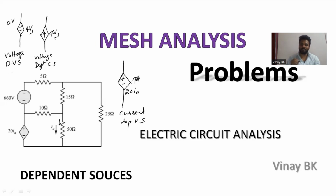One thing you should remember: if there is a dependent source problem, you should search where it has that parameter. For example, 20 IA. Somewhere in this circuit there is an IA value, so you should check. See, IA is here, so this voltage source depends on the IA value.